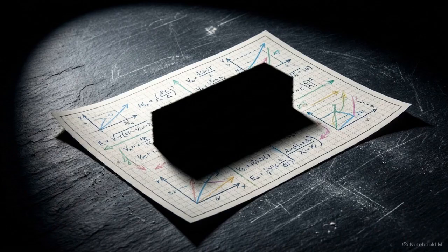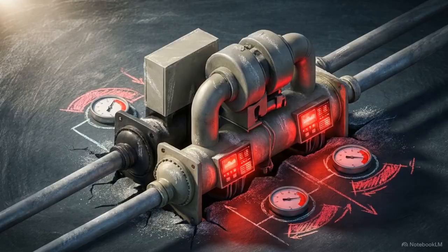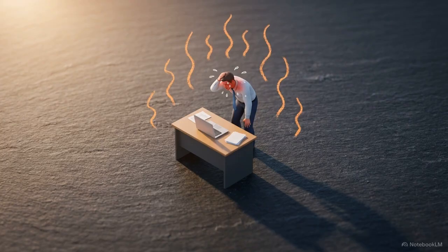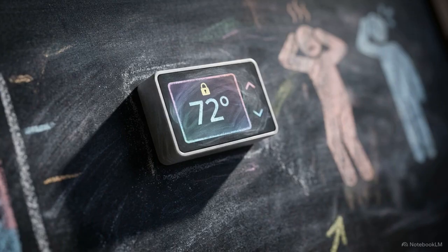The structure of this calculation sequence creates a severe blind spot. If the primary plant, calculated last in the chain, becomes overloaded and cannot meet the demands passed to it, the model hits a dead end. In reality, if a chiller plant maxes out, the chilled water temperature rises, coil capacity drops, and the physical room temperatures drift upward until the load matches the available capacity. The sequential model cannot simulate this room temperature drift.